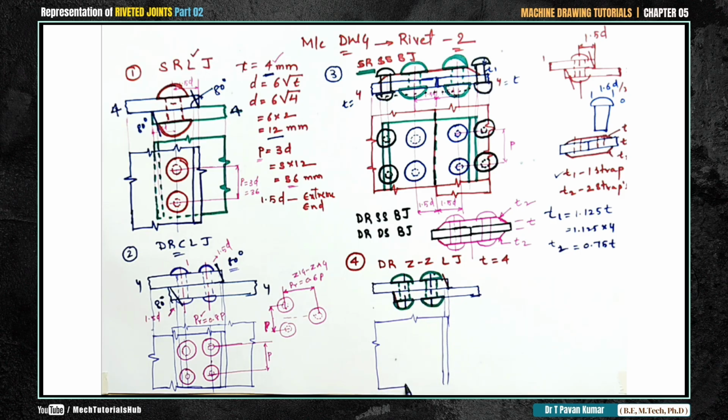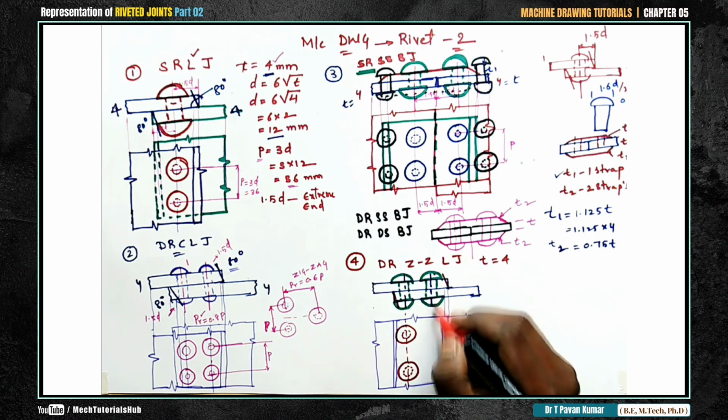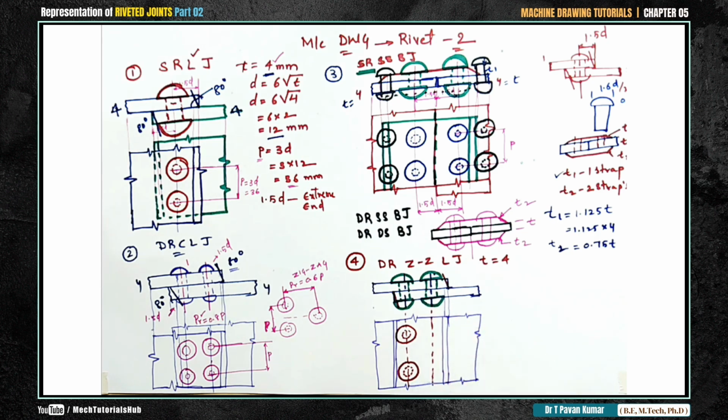Close it somewhere away. Sheet number 2, again you will get double line. This time I am aligning both the sheets. Now again draw the rivets position. If this is your axis line, D 1.6D, at a distance of P, D 1.6D. And one more row, this row will be added again. So at a distance of P by 2, there will be D 1.6D.